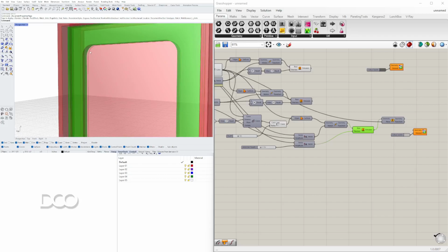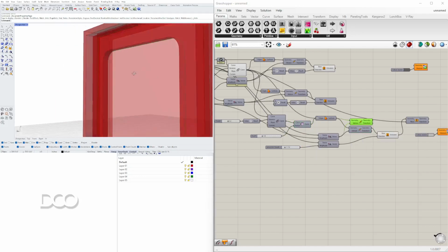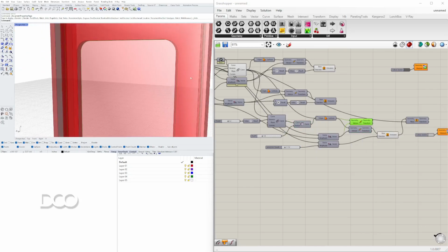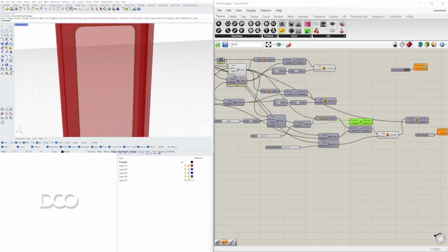So we'll take this form, which is actually created from this base curve, then turned into a surface, then moved up to here. So technically I have to move that same amount, and disable the preview on all of this, because with this, now I can create that solid.